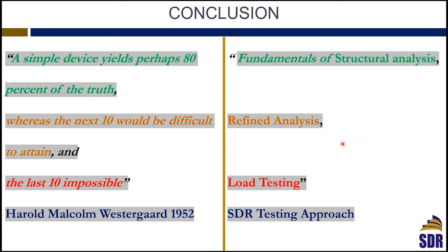And the last, impossible part, where we cannot get the real behavior of a structure, is why we are doing the load testing. With load testing, you can reveal the actual performance as much as we can, to account for the parameters that are impossible to account for in the design phase. So that's the way I can see things.